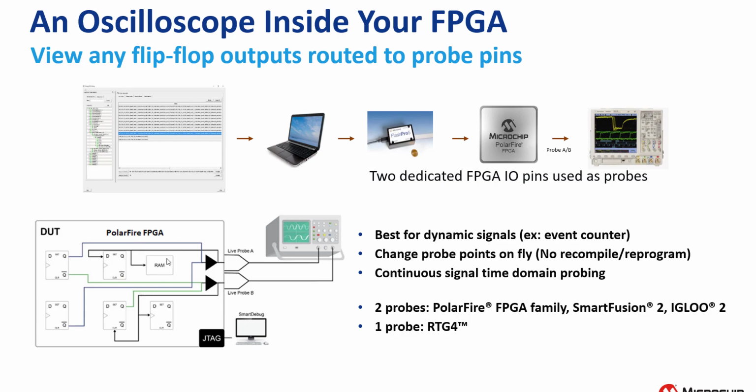If you have any doubts about a signal or memory, you can loop the known signals from channel A and channel B back into the FPGA fabric to write a known data to the register or the memory. This can help identify potential issues in the design. However, if you would like to use the loopback option, you need to use LiveProbe A and LiveProbe B macros in the design and reprogram the FPGA with the updated bit file before debugging.